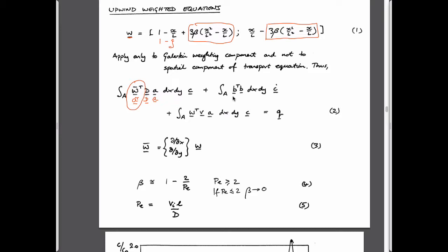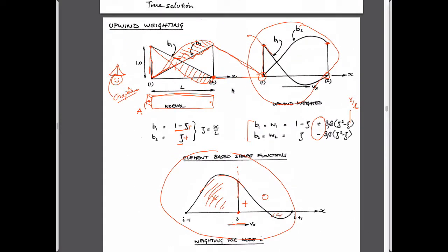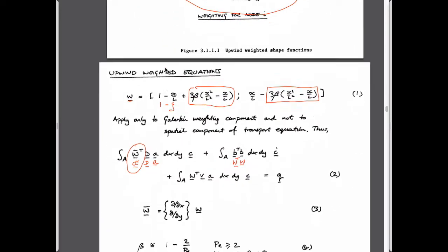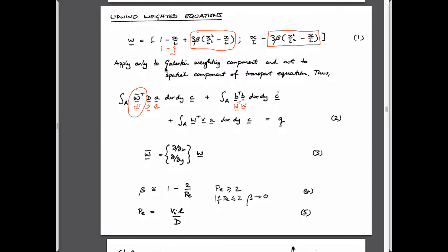We could use, I suppose, if we wanted to, W transpose W. I don't think it would make any difference, right, from what we know about this product of shape functions. The product of these shape functions is just the total volume of the element. And I think you can probably show from what we just said about this area here being exactly offset by this subtracted area here, that if you take the product of these shape functions, you still end up with the correct volume of the element, I think. I haven't tried it, but I think you would do. And so this is the capacitance matrix.